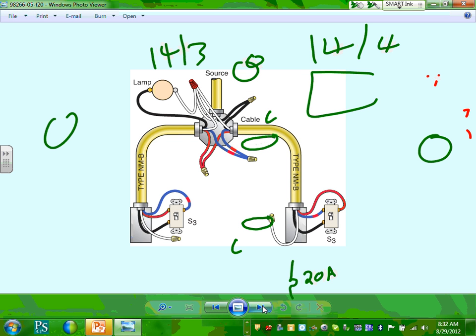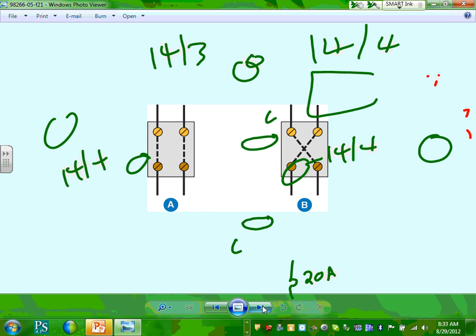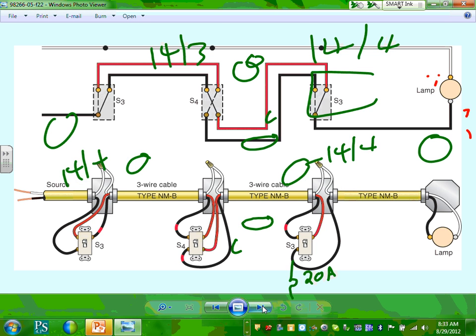Okay, a couple of applications, guys, sources and power. So what I suggest, again, with cables, look how there are just different scenarios where you bring the power to a light and come from both sides. In this case, we're still landing it the same. We're still using 14/4 here, right? You need the 3 for the travelers, 1 for the neutral, and of course the ground goes without discussion. Okay, so a couple of four-way switches.